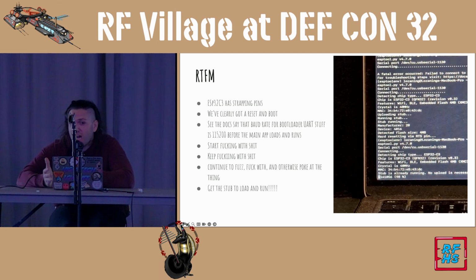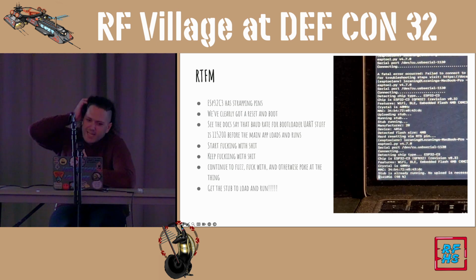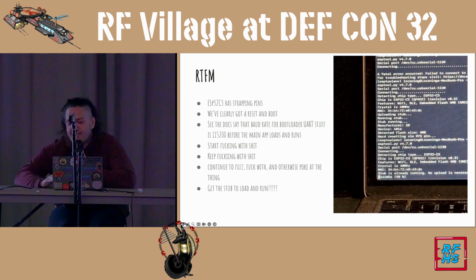And so eventually I went back to the documentation and read that. It's really amazing the kind of secrets that they hide away from you inside the documentation on the manufacturer's website. Essentially there are strapping pins on an ESP32, and for those of you who might not be familiar with microcontrollers, that's essentially a kind of spell or incantation you have to do on the device using the GPIO pins. Depending on what order you bring those to 3.3 volts or ground is going to dictate the mode that the MCU boots up into.